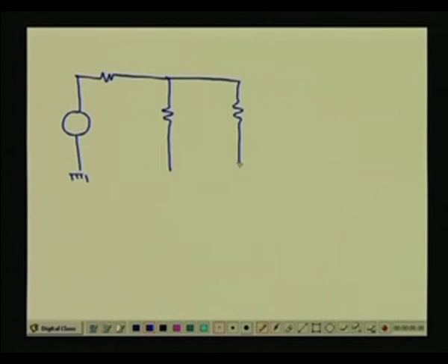Let me draw the equivalent circuit of the entire system. This is the pH voltage which we are getting, then the source impedance, then the impedance of the meter, then you have an amplifier with a gain of 3, because if you look at the values of Rf and R1, you will find the gain is 3. So, this is the output voltage.